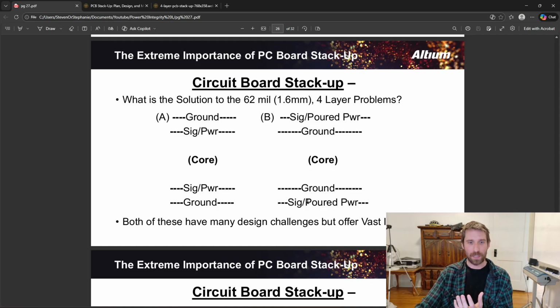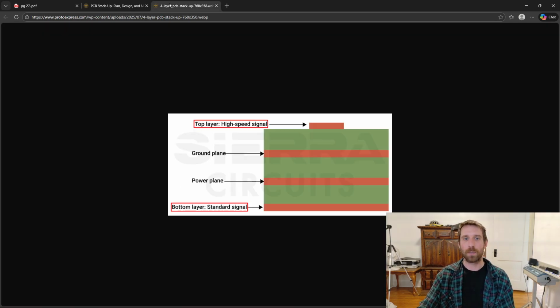So I get the advantages of external layers, thicker copper. I get the advantages of it's exposed to air, so heat can radiate out. And then I do the vias that make those two layers into one, kind of effectively. Now that I have two grounds, this also helps with ESD, by the way. So there's so many reasons to do two ground planes.